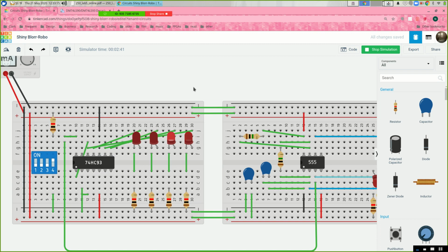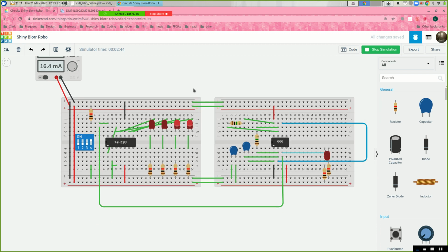All right, so this brings us to the original question, which is sort of the last part of this, which is how do we get this counter to reset so that when it gets to 9, it goes back to 0? So I've got a switch sitting over here. I'm going to try something. These 2 pins, 2 and 3, that I have connected to ground, instead of connecting those to ground, I'm going to connect them to a switch. So I'm just going to connect them right here. And with my switch on, those should be both connected to ground, so this should still be counting as usual.